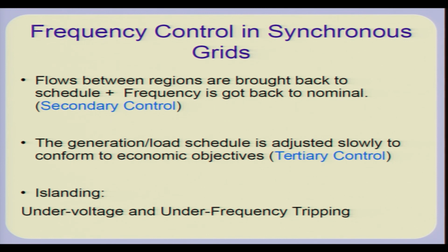Of course, inadvertently sometimes due to loss of synchronism etc., you may find that a synchronous grid may split up into various regions, and they are disconnected regions, and these are called islands, and now within the island you need to maintain frequency and voltage, and usually the disturbances which cause islanding are quite significant or large impact disturbances, and the frequency and voltage variations may be quite significant, and we may have to rely on additional measures like load tripping, under frequency or under voltage load tripping, to ensure stability of frequency within a disconnected island.